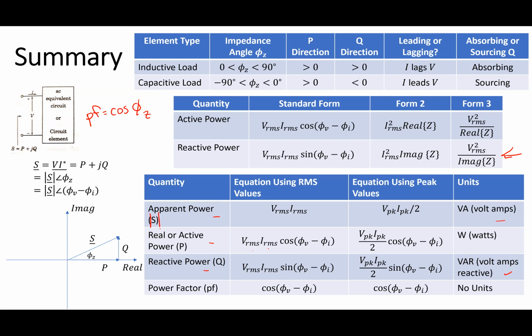There's the trick. Cosine, for all of these loads I'm talking about, real loads, inductive or capacitive, are only going to be in quadrant 1 or quadrant 4. What's true about cosine in both of those quadrants? The cosine of the positive and negative angle is the same. So if I give you a power factor of 0.9, you don't know whether that is the positive angle or the complementary negative angle. So I need to give you more information to figure out which one it is.